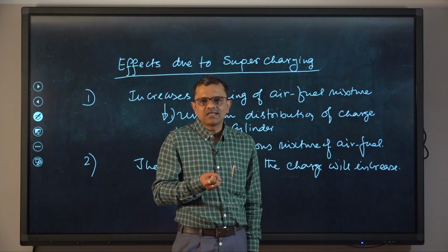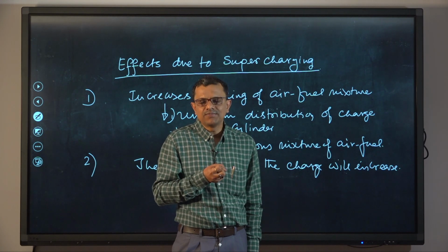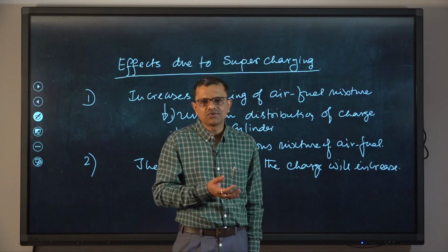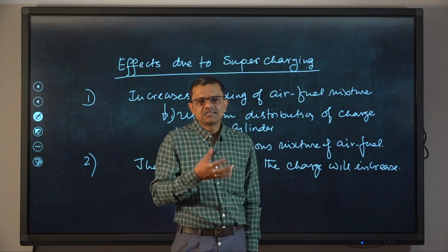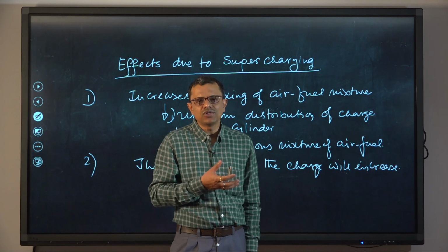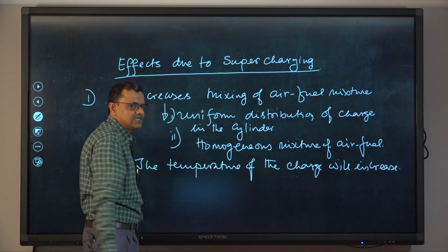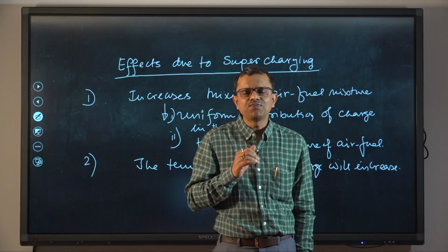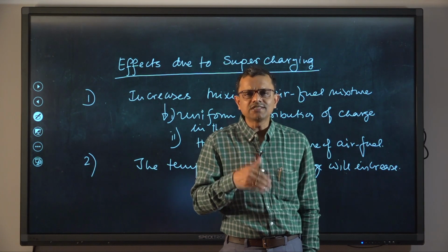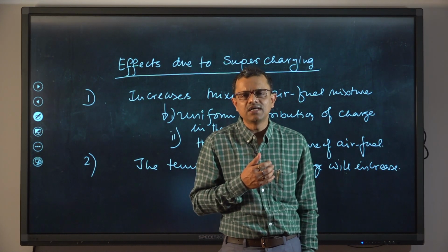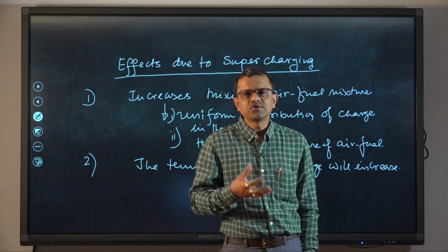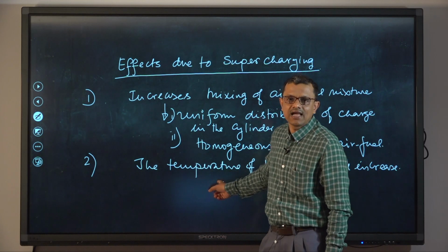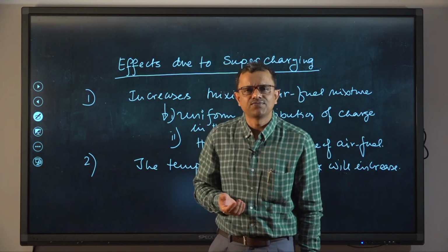If the charge already has a higher temperature in the intake stroke, the temperature will increase even further during the compression stroke. So, essentially the chance of detonation will be more with this effect, that is, increasing the temperature of the charge. Despite the favorable aspect of efficient vaporization of fuel droplets in the intake manifold, higher temperature may lead to the possibility of detonation for SI engines. On the other hand, this higher temperature can reduce the possibility of detonation for CI engines.